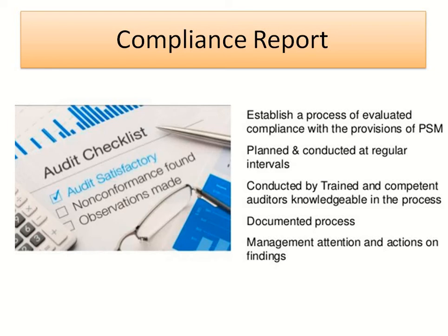Establish a process of evaluating compliance with the provisions of PSM, process safety management, planned and conducted at regular intervals, conducted by trained and competent auditors knowledgeable in the process, with documented process and management attention, and action on findings.